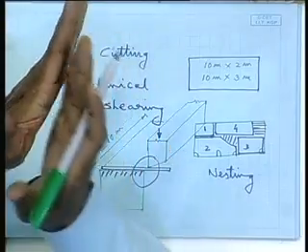And in the process, the cut edge is obviously subjected to a stress level much beyond the elastic limit. So, the cut edge will have tensile strength more than the rest of the plate. That means that part will be harder, that is, work hardening will take place, because if we see the stress strain curve, it will be quite above the yield point stress. So, that cut edge will be truly work hardened.